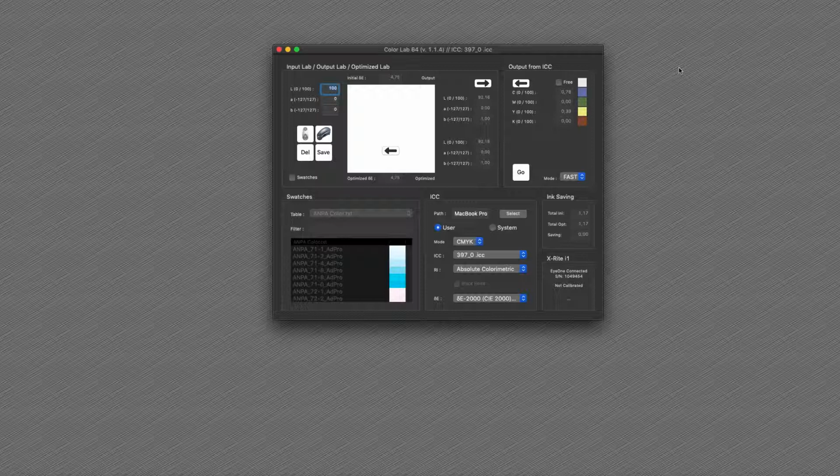First thing we need to get is a LAB color that we get here. You can type the color number manually, for example 45 10 25, and here you have the LAB. If you want to delete this value, you can click on delete, and it's going always to the default value 100. Second way of entering LAB values is by measuring.